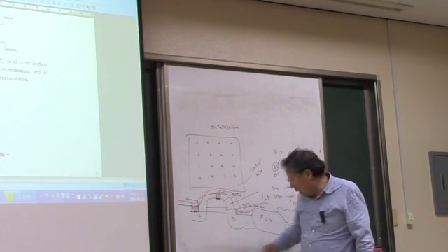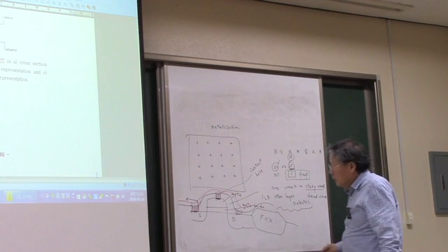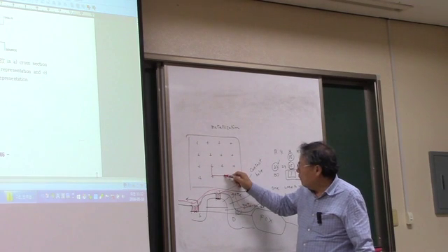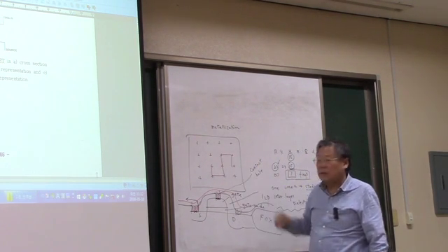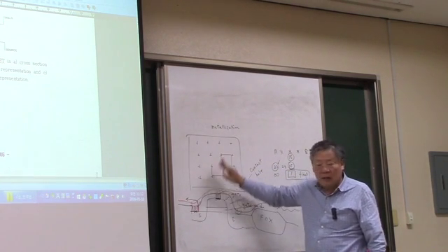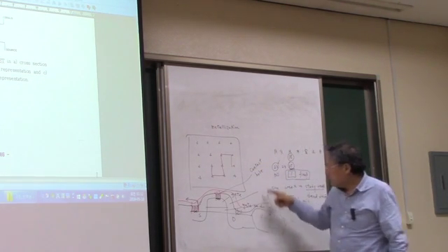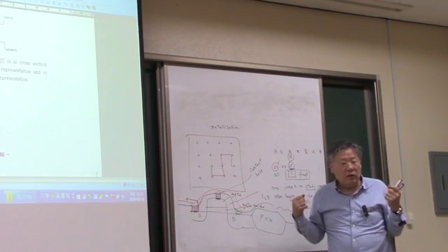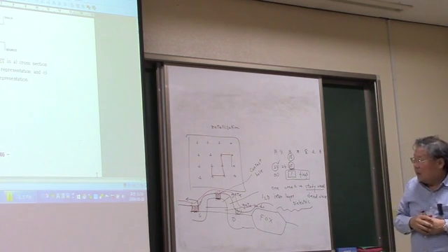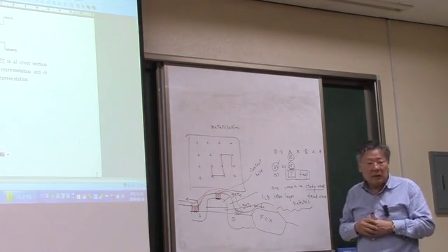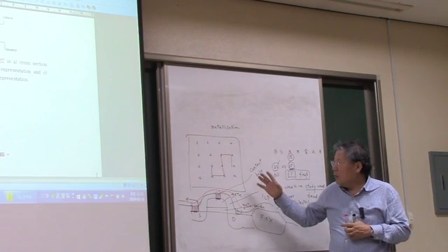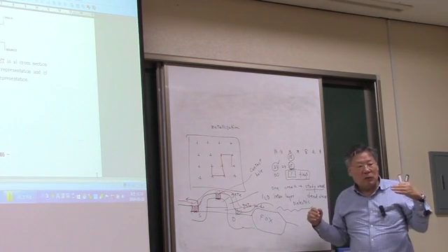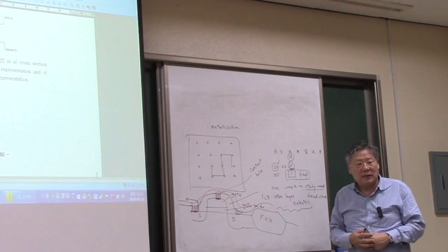And then you etch this, except the lines that we need for the interconnection to form a circuit. And other metal deposited on top of the interlayer dielectrics should be etched off. We can use wet etching, we can use dry etching, but commonly we use wet etching because it is very difficult to etch metals with a dry etching process.